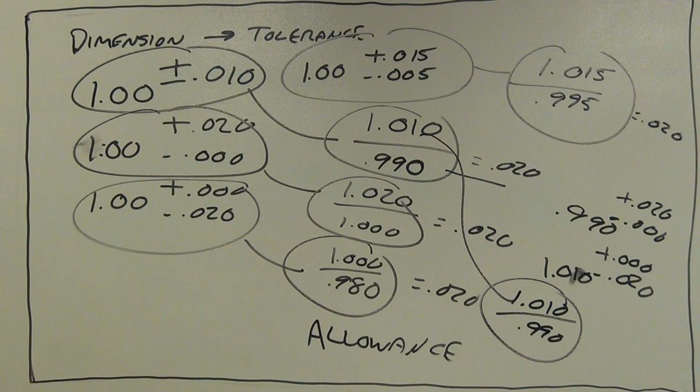So it's not unheard of to have a drawing with all three place dimensions where only a few instances would a plus or minus 5 tolerance even be necessary. So anyway, that's how I feel about default tolerances. I'd like to see them expressed, but the way they're expressed in this way can be problematic. And the very best thing you can do, I think, is to take whatever form you get and at least work out the limits. And that way you don't have any math to do in your head while you're trying to address that feature.